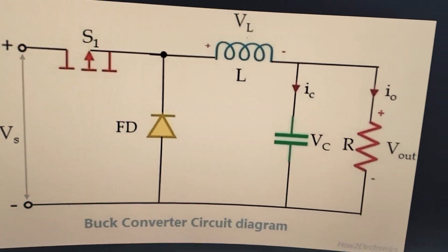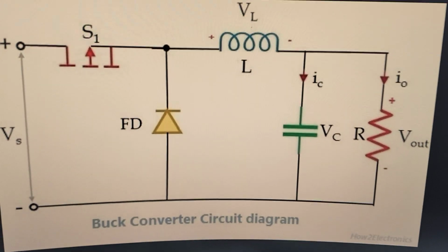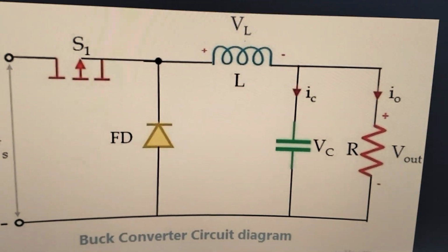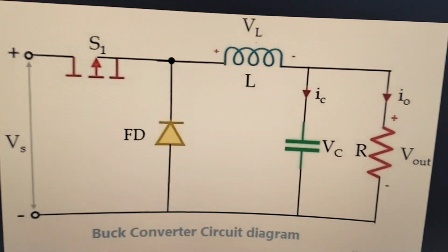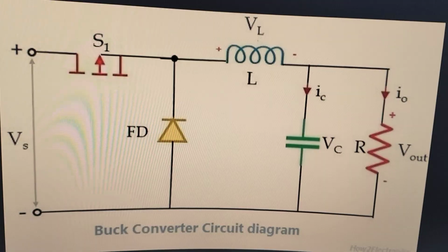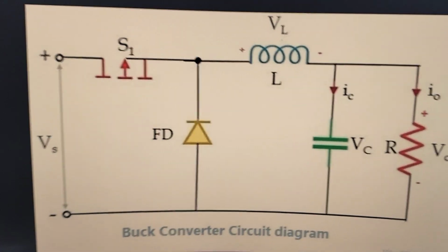And of course we have done the buck in the past, but we did that with the TL494, the PWM IC, and it was fully analog or discrete, whatever you want to call it, and it was open loop. So basically, we were varying the duty with a pot, and we were able to see the entire range.